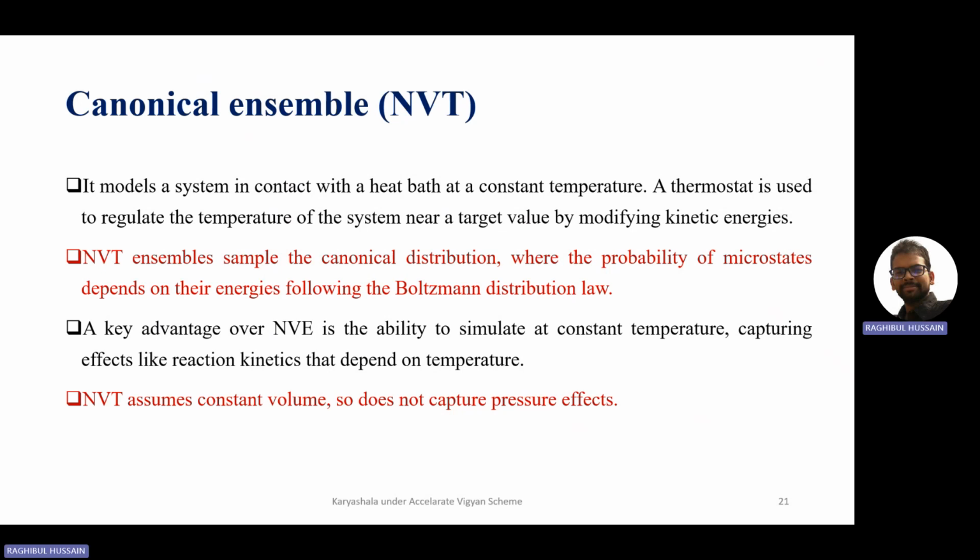Now, in the first half of this lecture, I said that we need the thermostat as well as the barostat to keep our system stable. During our MD simulation, the molecules are moving and colliding with each other, and therefore the temperature increases. But in the NVT simulation, my temperature will remain constant, that means within a certain range.